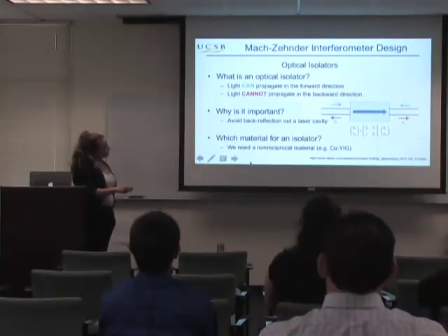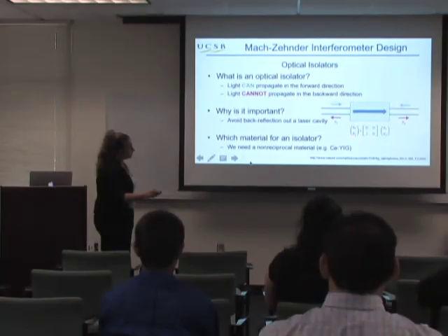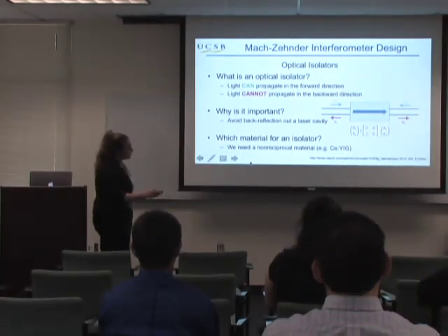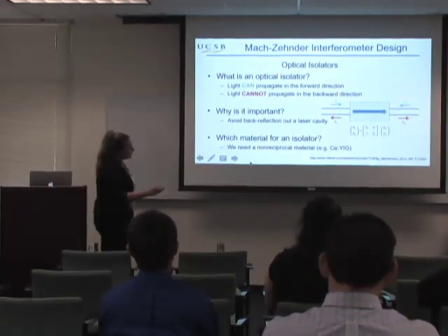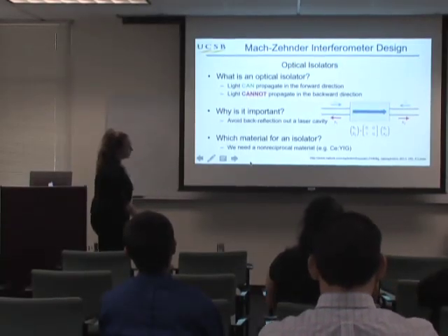In this diagram, you can see a schematic of a single mode, two waveguide optical isolator, wherein the matrix there is full transmission in B2 in the forward direction and zeros in the backwards direction for A1, A2, and B1. So there's no transmission in the backwards direction and only in the forwards direction.